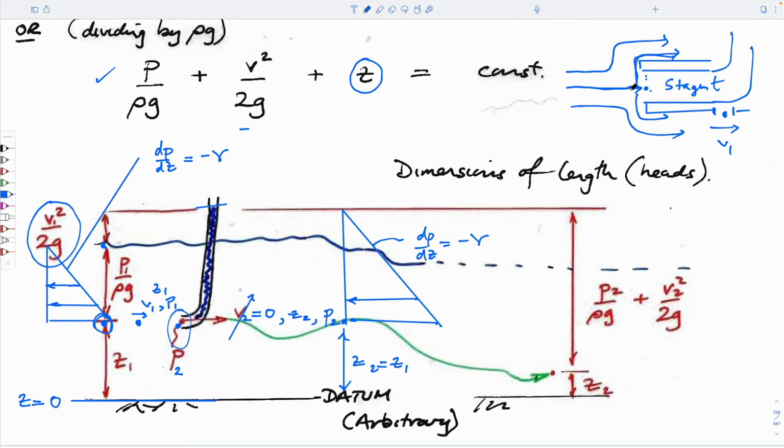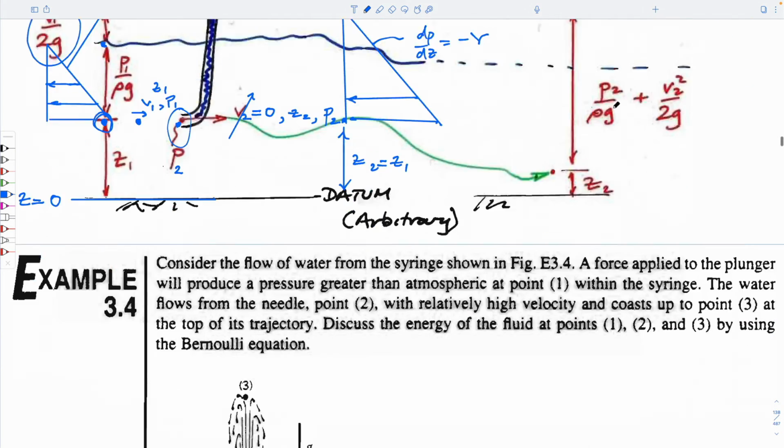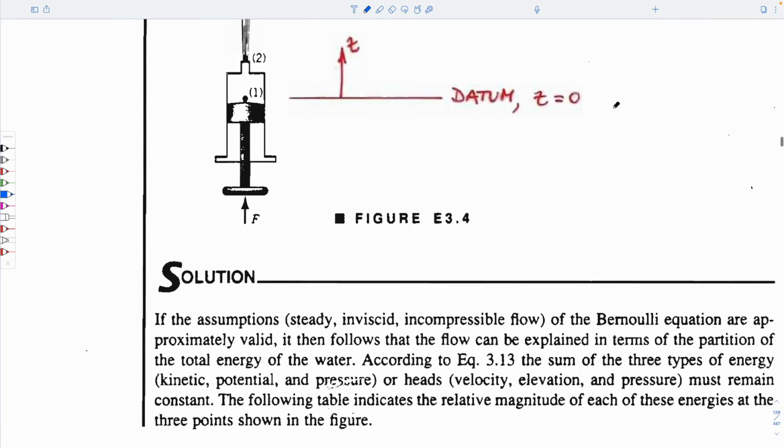And the plane went up and down because it was getting wrong signals to the remote pilot and ultimately never arrived in Paris. Everyone was lost. And so now they have heaters in these things so that when you go through thunderstorms and it's minus 60 outside and also wet and it will freeze ice on it and seal this, it's able to melt. And so contrary to popular belief, for fine tuning of velocities, it's measured directly, not from GPS, although it's obviously measured by GPS as well.